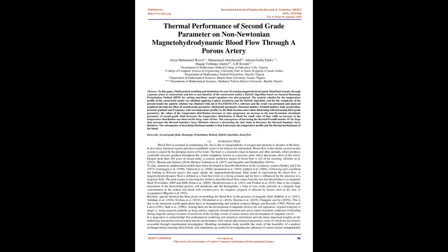result was presented and analyzed graphically showing the effect of second-grade parameter, third-grade parameter, Hartmann number, Prandtl number, body acceleration, pressure gradient, and frequency ratio on temperature profile. As the fluid becomes more shear thickening with increasing third-grade parameter, the values of the temperature distribution increases as time